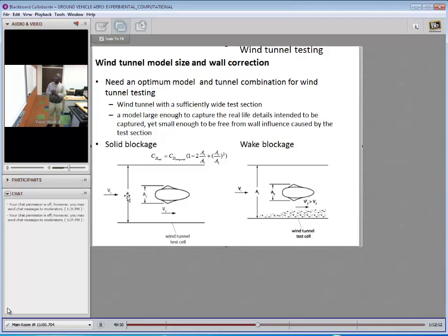One of the things that we compute in designing the vehicle is the drag coefficient. Again, remember, we want to minimize drag, and so we want to reduce the drag coefficient. Tests that have been done indicate that the real drag coefficient is obtained by using this. The computed drag coefficient is what we get from calibration, the calibrated value when we put a test section in there, and that calibrated value is done in the test section area.